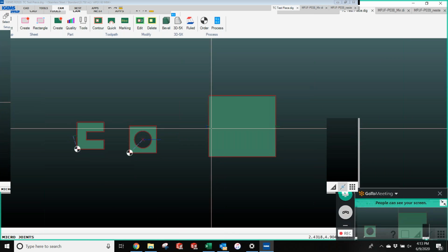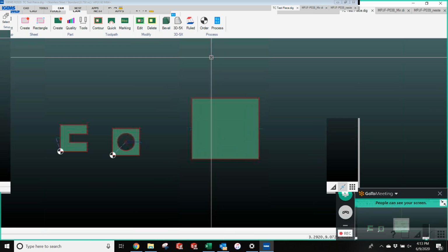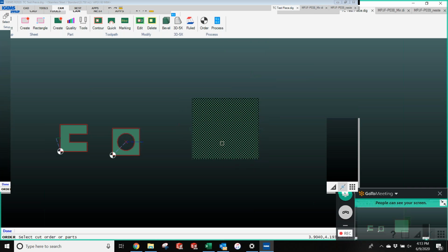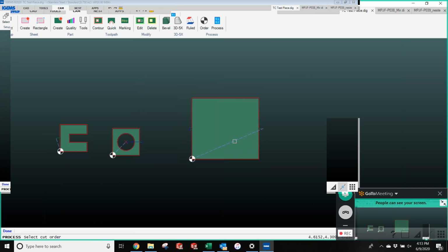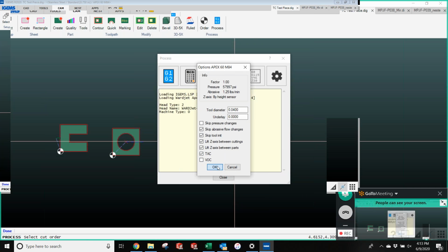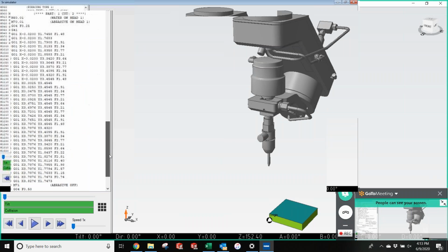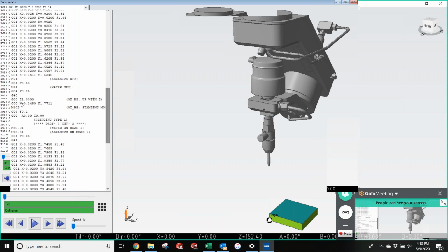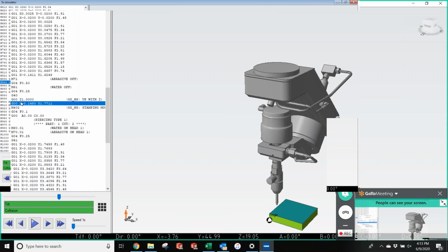Okay. And I saw that in one of your webinars, but when I'd already created the part through the 3D 5X and then come into the 2D world, it will not allow me to add that in the toolpath, and that's where I couldn't figure out what I was doing wrong. Yeah. Okay. Makes perfect sense. And this should work. It's going to come up over, and then it's going to height sense.